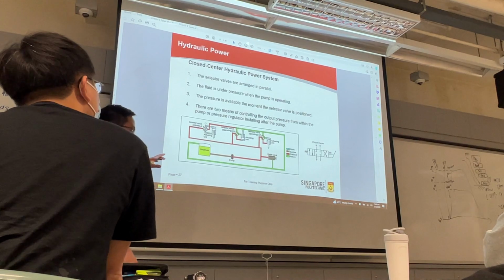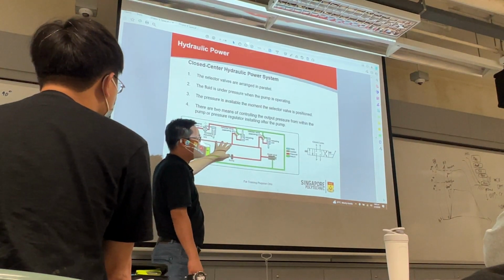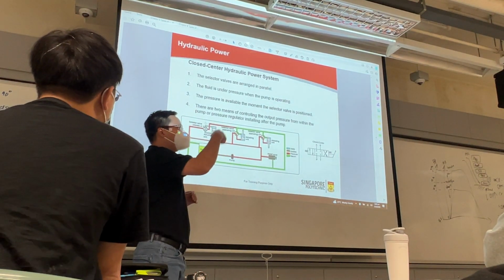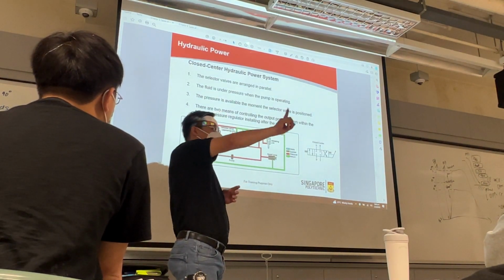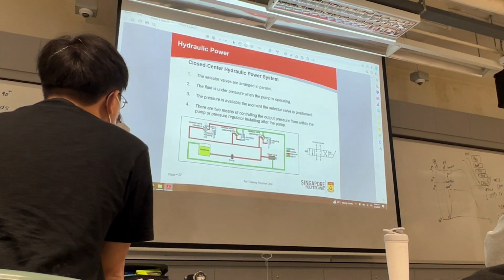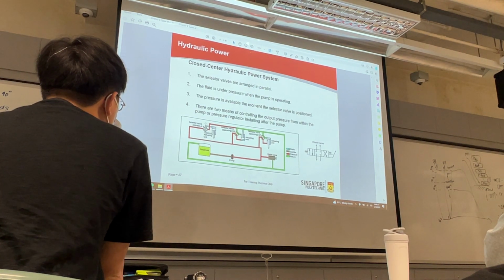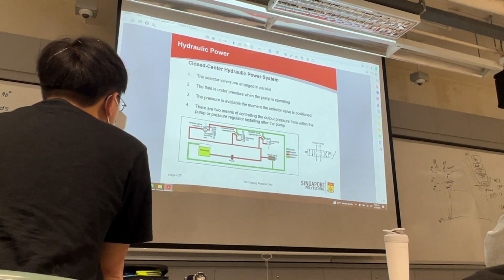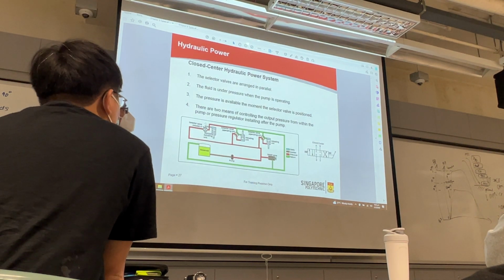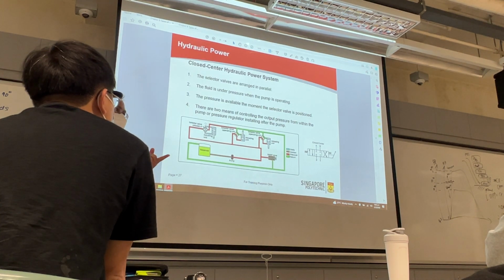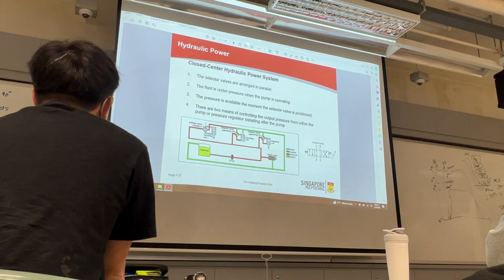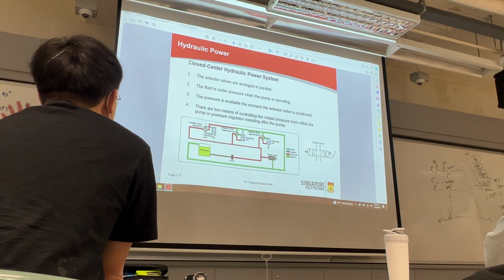Give an example, I've seen it before. The pilot comes down and tells me my pressure gauge is fluctuating, from 1,000 to 3,000. Then he says, I think your system got problem. I ask him, at what phase did this happen? Cruising, climbing, or descent? He says, just after takeoff, climb. Then I ask him, what are you supposed to do? He said, retract the landing gear, then retract the flaps. Do you do it at the same time? Then suddenly they're very quiet, and the aircrew suddenly move away. Then I know, and they come back and say, yes, we did it.